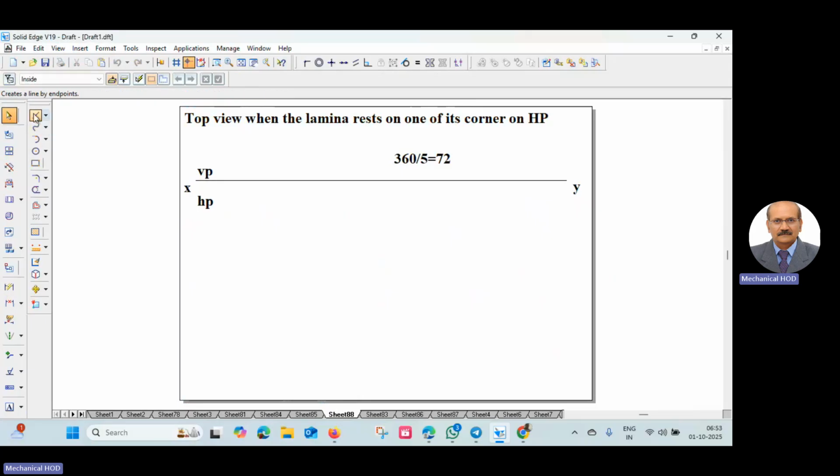Let me start with the triangle. 30 mm or 40 mm is the length of the triangle. First angle 0, then 40 and 120 degree, the external angle for the triangle. Next 40 is the length. Next angle is 120 into 2. So you got a triangle.